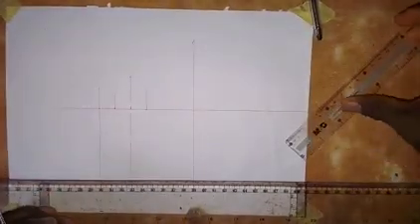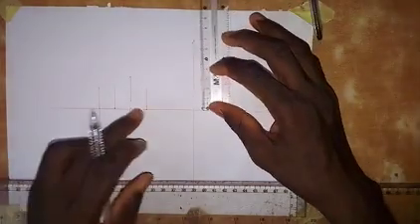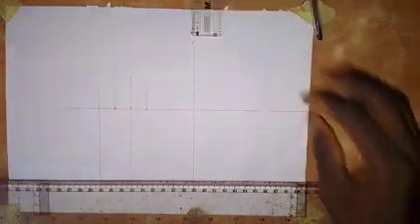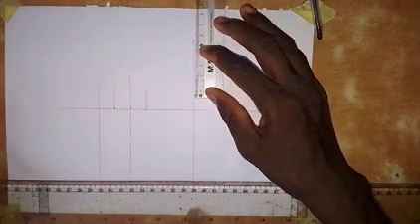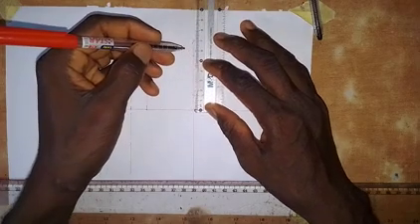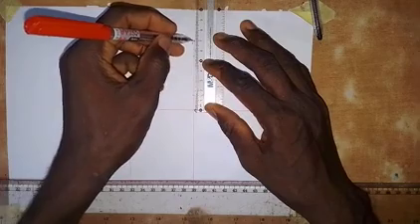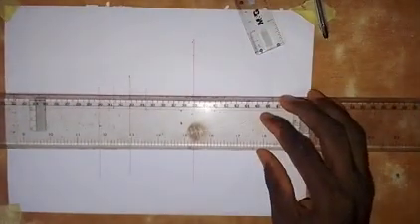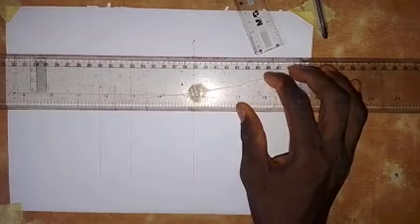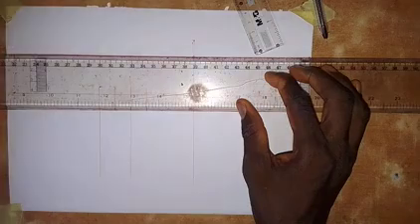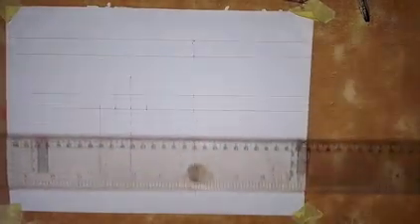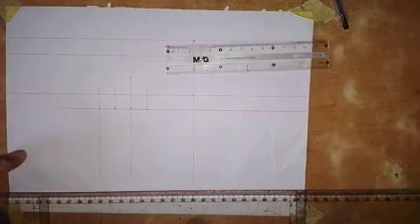So the next thing that I'm going to do is take the thickness here. Here we have 15 millimeters as the thickness, as we see it there. Then from this 15, I'll take a measurement of 40 millimeters up. This is 40 millimeters. Then I will take the total height, which is 70 millimeters. This is 70 millimeters. So for this distance that we have taken on the vertical, we have to draw a horizontal line to both sides, because of the end elevation that we are going to draw. Okay, so we also draw this line. Alright, so let's take the thickness as we see it here.